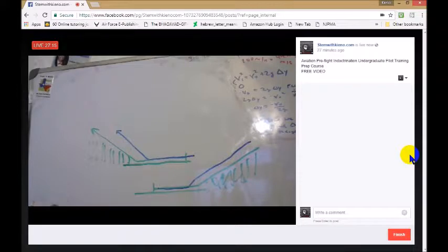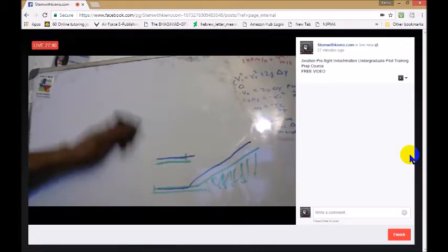You're trying to generate lift, and the last thing you need is something disturbing you. So that is something that we need to be cognizant of when we are taking off or landing behind larger aircraft. Wake turbulence and wingtip vortices.